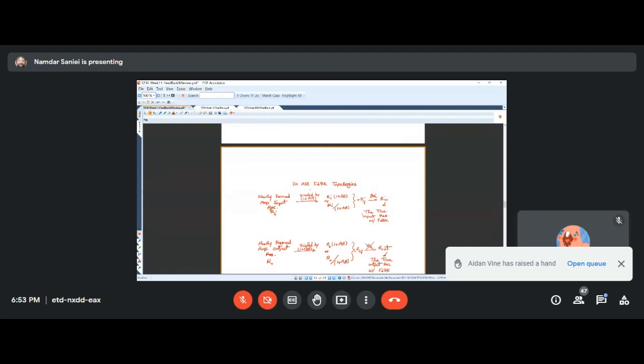The RI is the input resistance of the newly formed amplifier, which gets scaled depending on whether we have series or shunt at the inputs. Whatever comes out is what we call RIF, but that's not the true input resistance with feedback. We had to extract RS to reach that Rin, which is the true input resistance with feedback.